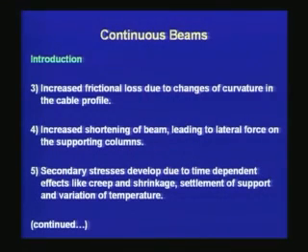The fifth disadvantage is secondary stresses develop due to time dependent effects like creep and shrinkage, settlement of support, and variation of temperature. The continuous beam is a statically indeterminate structure, and hence it is subjected to secondary stresses which come due to the movement due to creep and shrinkage, due to variation of temperature, and due to the settlement of the support.